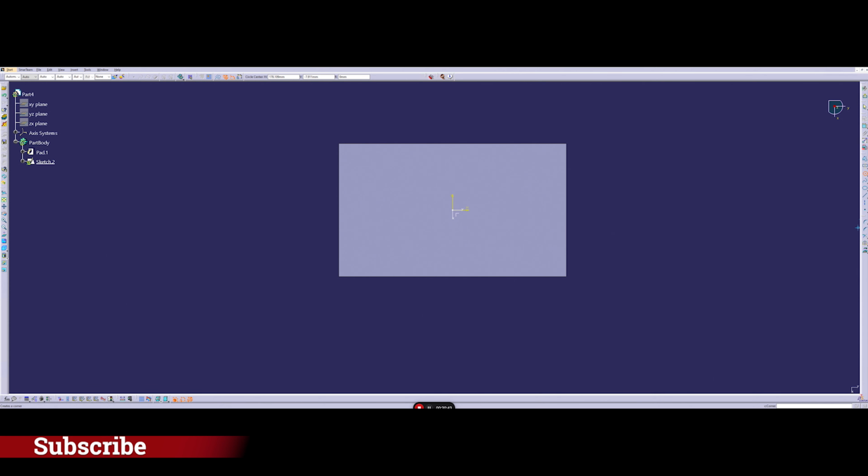So actually here we can choose the point command, and we can come, let's say, to this point, click, and press escape in order to release the point. So now we have to go here, double click the dimension constraint, click here and the edge, and we create a dimension which is 20 millimeters.